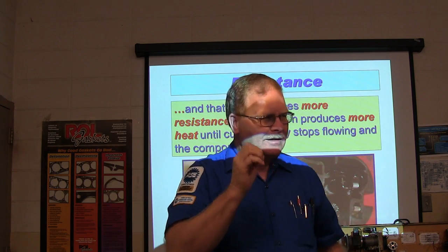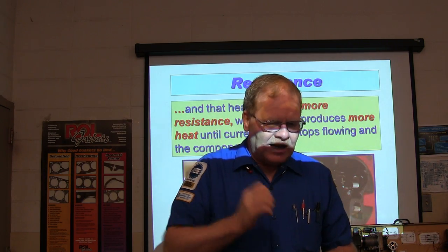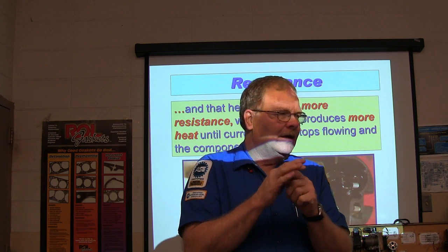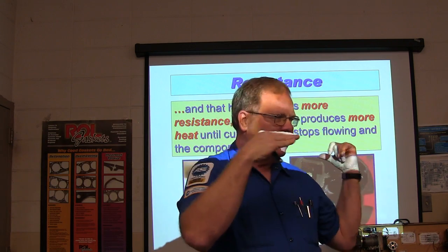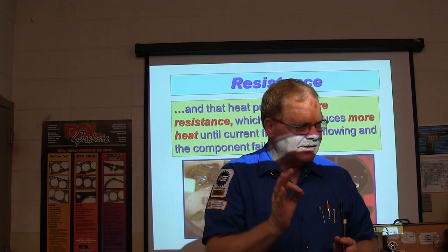And here's another thing. Don't take a test light when you're checking a connector and ram it down in there so you spread the terminals. Don't ever do that. Because when you plug it back in, it's not even touching, or it's barely touching, and then you wind up with this. So don't ram anything down in there to spread the terminal. Just touch it very gently.